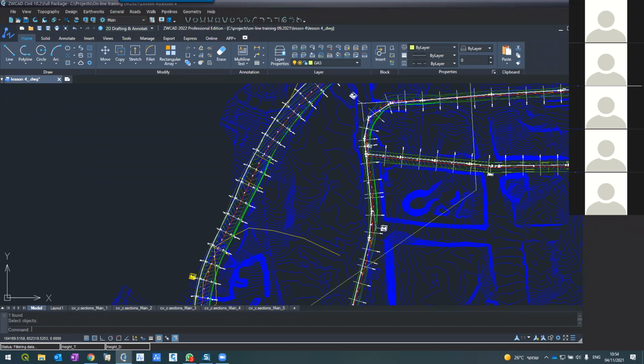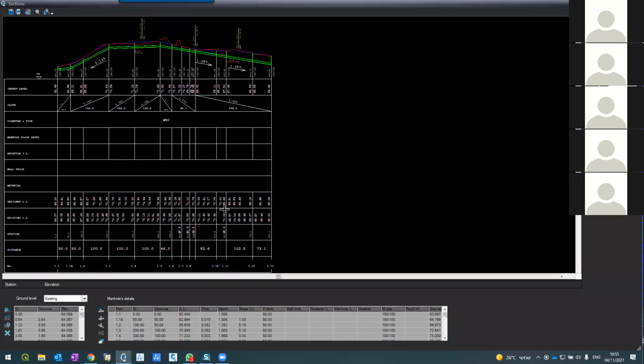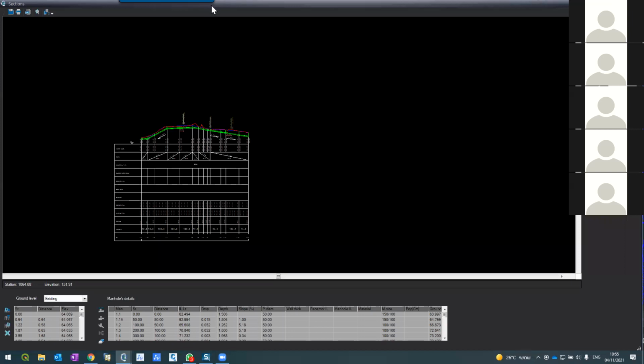So again, the gas company gave me the layout of the pipe. It gave me the depth of the pipe. It says 2 meter. This is taken by default because we don't know. We don't have it in 3D. We don't know the exact depth. And the diameter is 20 cm. Now the layer, of course, and the station were extracted from the layout. If I go now to the sections, see what I get? Sorry, let me remove this. This is coming from here.